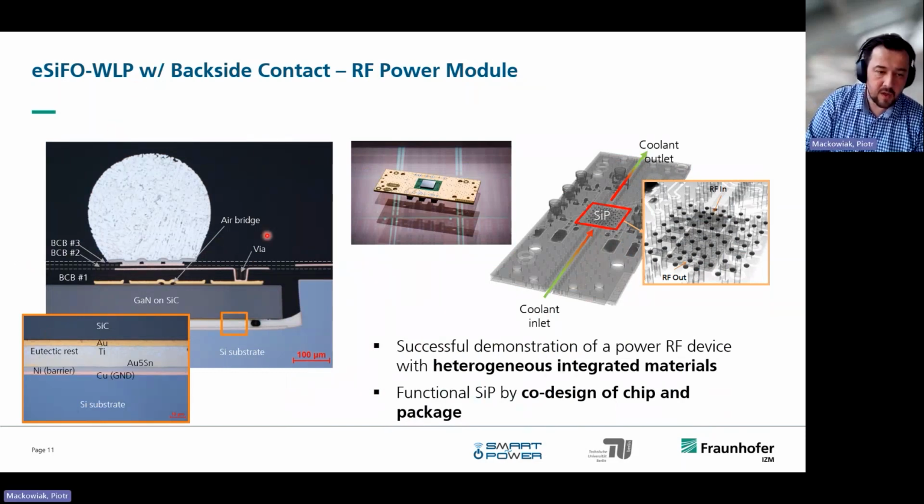On this slide, I would like to give you the final assembly of the device and a cross-section of the device assembled here. The cross-section on the left side shows the GaN chip grown on the silicon, which is then soldered on the bottom of the cavity, with the metallization scheme shown on the bottom. And as mentioned before, you already see one of the problems here. This is not perfectly leveled, but still handleable. But it's a very good example of the challenges I mentioned before.